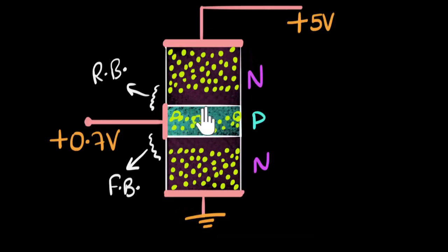And the recombination chances over here in a transistor is very, very small for two reasons. One is because this P region is very lightly doped. So there are a small number of holes to begin with. And as a result, the recombination chances are small. But the second reason is that this is very thin. And as a result, most of the electrons that get injected over here will find themselves already at this end. And as a result, they can now be pulled by this voltage.